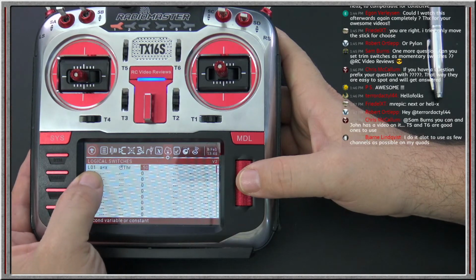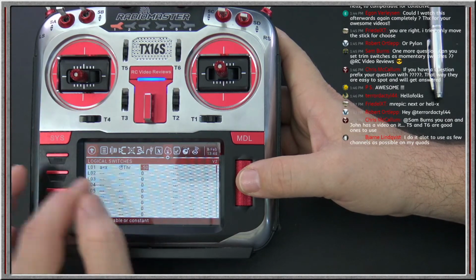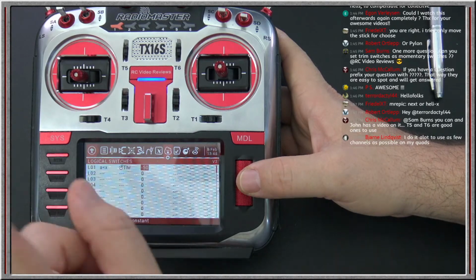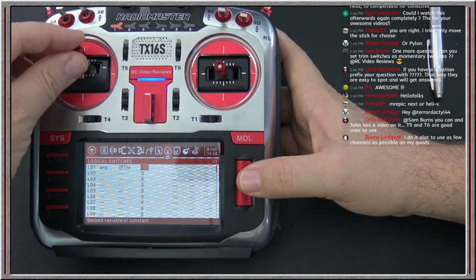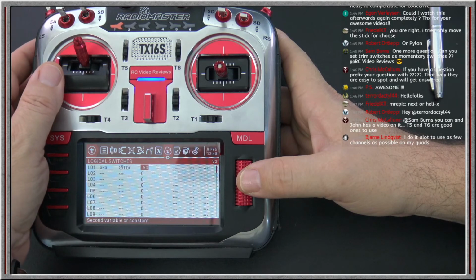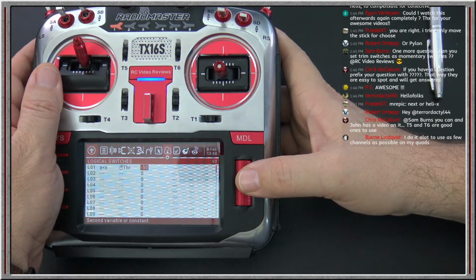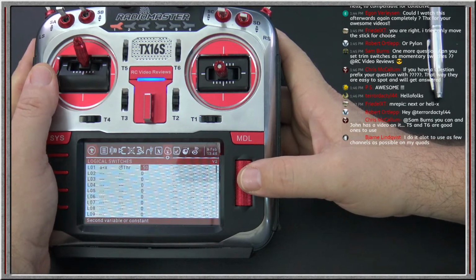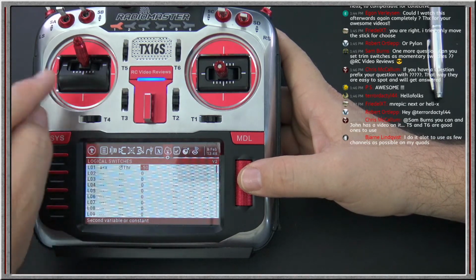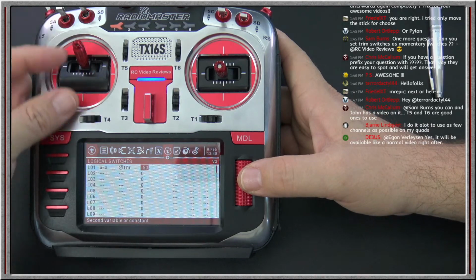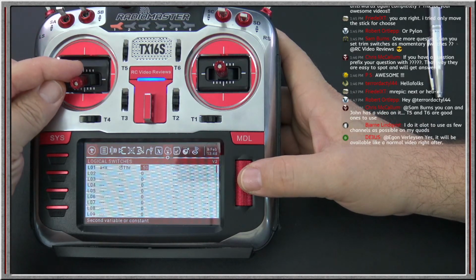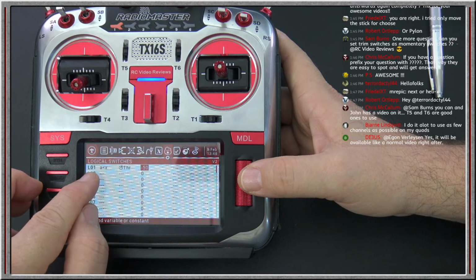Okay? So I'm going to assign L01 to say, when my throttle is advanced, I don't really care about the elevator flap mix. If I'm using flaps, I might be doing it for an aerobatic maneuver, for example. So L01 doesn't go on when the throttle is above about 75%. When I bring the throttle down below 75%, you see how L01 goes on.